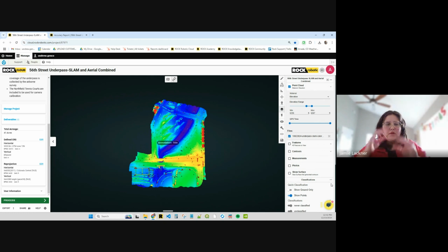I feel like something we also learned is that you collect GCPs, but something that happens that I do with the data quality assessment, I will go in, and very often, obviously in this case, Andrew and the rest of the team collected the GCPs with the best of intentions. But if I find a particularly erroneous GCP, one that really shouldn't be a GCP, I cannot tell you how many I've seen on top of raised manholes, on ledges, on things that really just aren't ground, ultimately what we have to do is turn that either into a checkpoint or disable it.